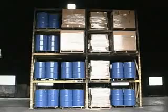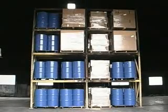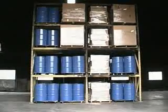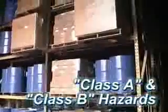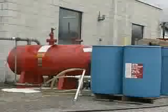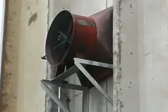The 17-foot-high storage racks were assembled in Ansul's large indoor test facility and stocked with corrugated cases containing 720 gallons of mineral spirits in 1-gallon F-style plastic containers, representing a Class A combustible and Class B flammable liquid fire hazard. The test required 2 JetX 15A high-expansion generators with a total foam output of approximately 35,000 cubic feet per minute, based on an inlet pressure of 75 psi and using outside air.